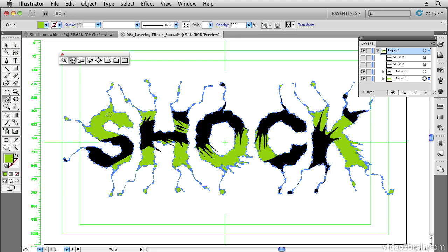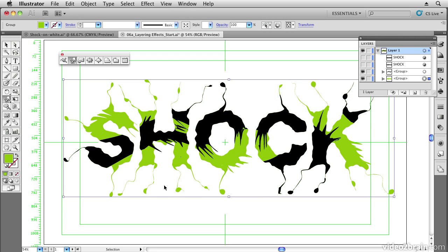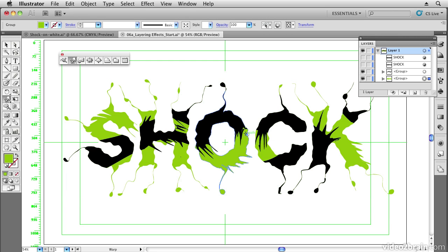And just have a bit of fun with it, sculpt it, cut pieces into it by pushing the path and pull pieces out. Every now and then you may need to look at it without the selection, so you can hit Command H to hide the selection, and that allows you to continue working on it without seeing the selection. So I want you to be a little bit experimental and have a play with this and see what you can come up with in terms of your design.